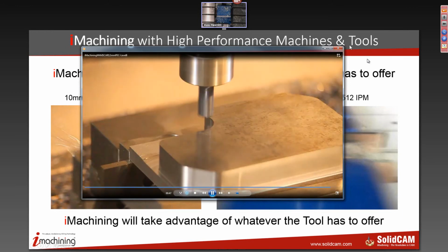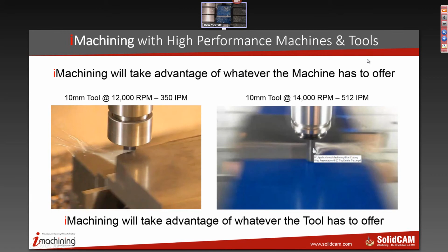You've got to use the right equipment. If you're going to get seriously aggressive and start really doing some high performance cutting, I like these RegoFix power grip systems. They have more holding power than the shrink fit holders have.